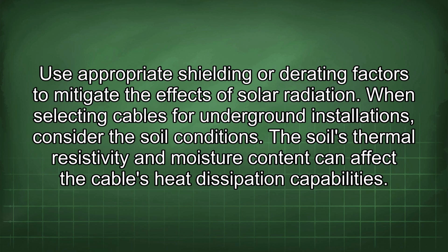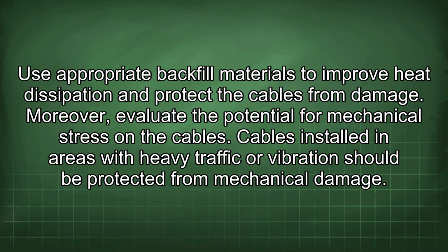When selecting cables for underground installations, consider the soil conditions. The soil's thermal resistivity and moisture content can affect the cable's heat dissipation capabilities. Use appropriate backfill materials to improve heat dissipation and protect the cables from damage.